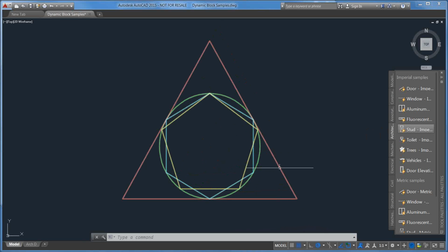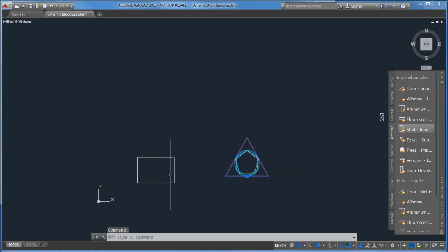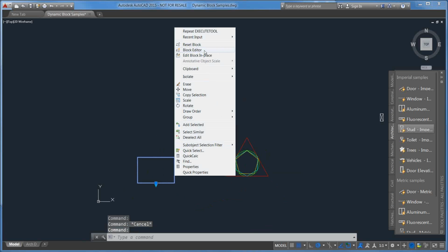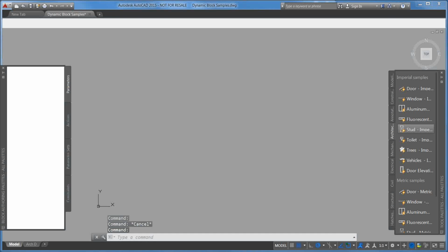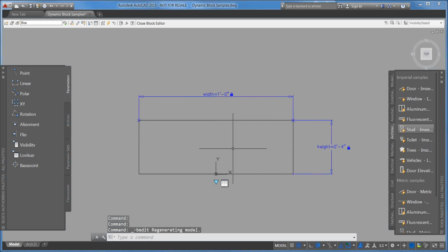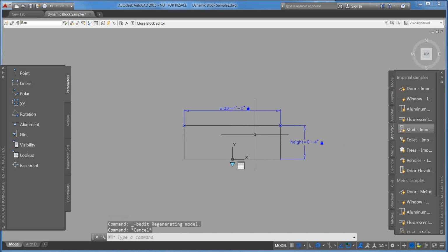And then Chris asks, is there a way to count similar blocks that have different rotation properties from the dynamic rotation grips? B count and select similar don't seem to work if the rotation values are different. Yeah, so the B count is kind of, I guess, more of a basic, how many blocks are there of this name? It doesn't look at the parameters when you adjust them.